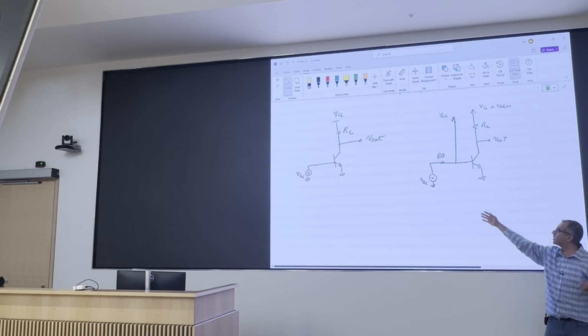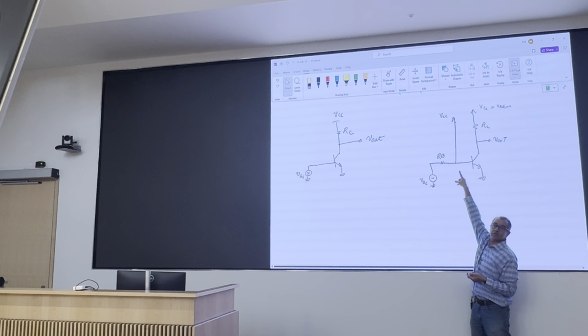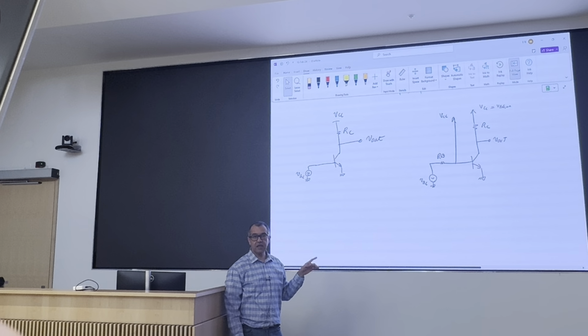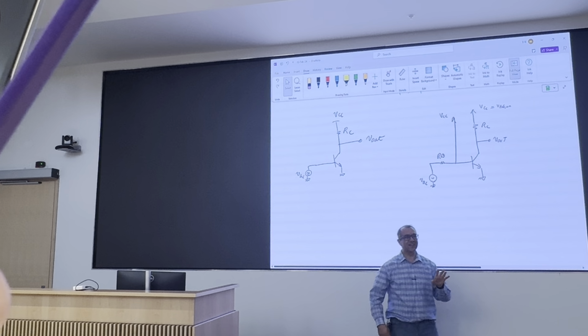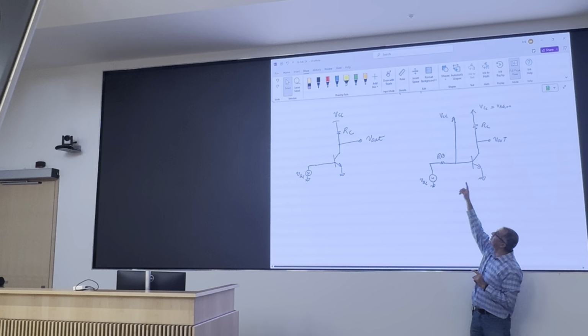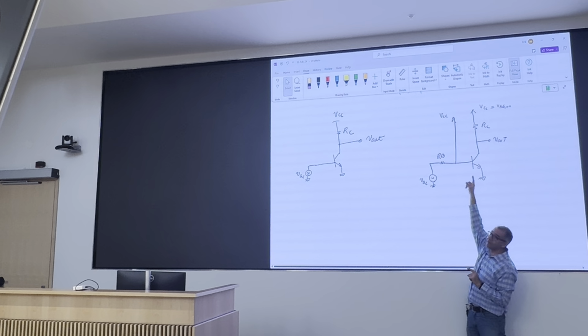Right? Because you put a voltage source here. Once you put a voltage source here, that voltage is fixed. The poor transistor doesn't even see the signal. All of your signal dies across that RB. It doesn't even get to your transistor. If you try to be smart and remove RB, then I will kill you. If that guy doesn't kill you, I will kill you, because then you're going to damage his power supply and the transistor.